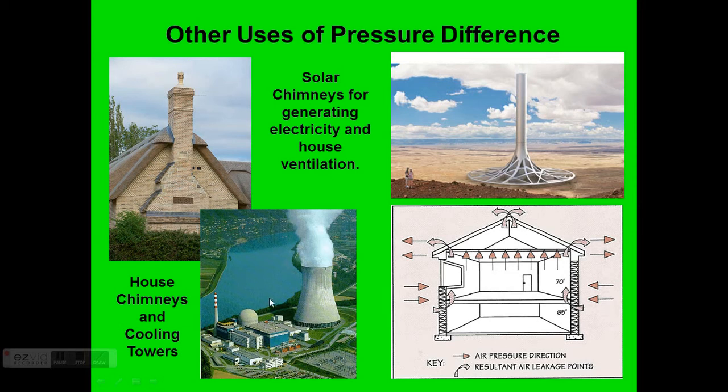Imagine this for Three Mile Island. This little dome here is the reactor building. This is a cooling tower. Basically what happens is we draw water in from the river. It's used in the reaction to keep things cool. The water is not radioactive, but it's too hot to stick back in the river. So they put it in pools at the bottom of these cooling towers, and because of this unique shape of the chimney, we draw maximum airflow across that pool of water straight up the chimney to cool that water before we can put it back in.